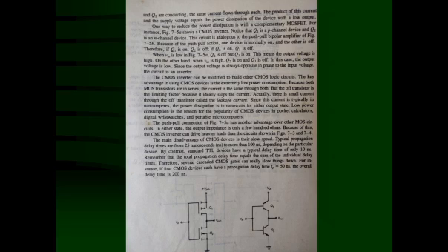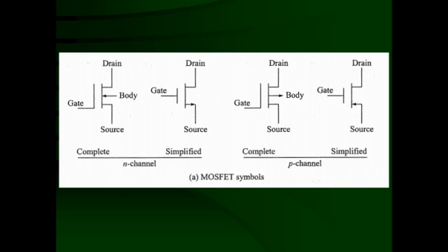In TTL, standard TTL has a propagation delay time of only 10 nanoseconds. Here it varies from 25 nanoseconds to more than 100 nanoseconds, and it is additive when a number of gates are added.